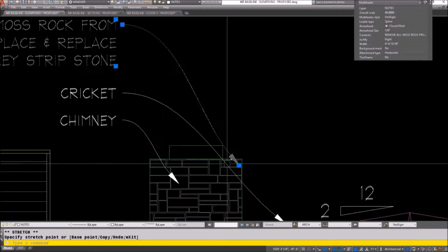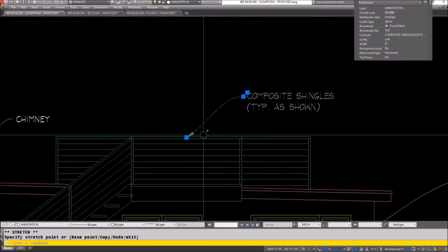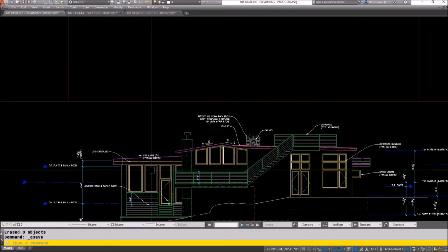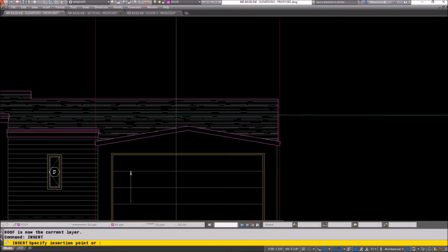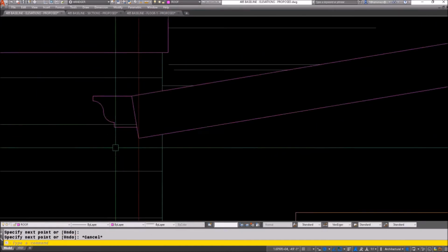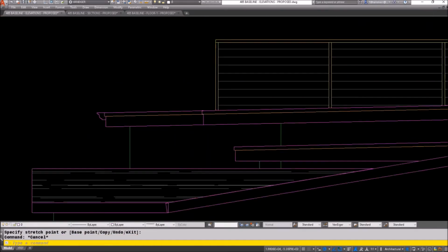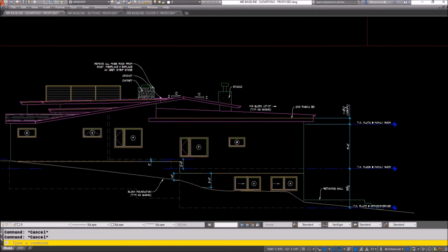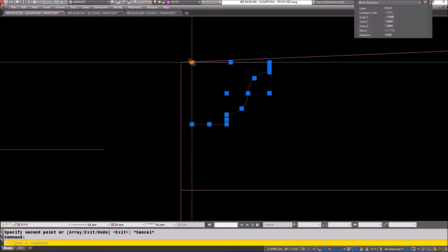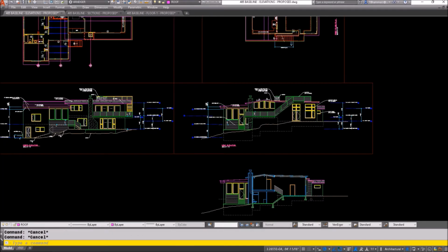One of the things I've done to accelerate my performance is when I'm in a drawing like this, I select an XREF, an external reference drawing. I right click, hit X, and it opens that drawing immediately, automatically. I've got that set to do that. A lot of people do. It's just so fast. Then you do all the corrections in that XREF, and then I hit right click Q, and what it does is it zooms to the extent of the drawing, saves it, and then closes it. And then I'm back in the original drawing that I was working in that had the XREFs.